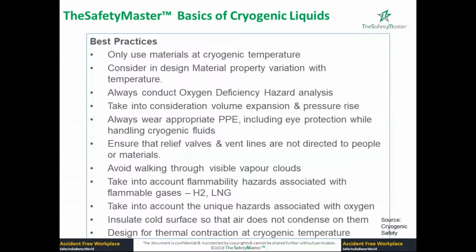What happens is the liquid nitrogen or liquid oxygen, whatever it is, will freeze your eyes. You will not be able to see, so somebody has to help you, or you need to go to the nearest shower or nearest wash basin. You have to simply keep the water flowing for 15 to 20 minutes near your eye.